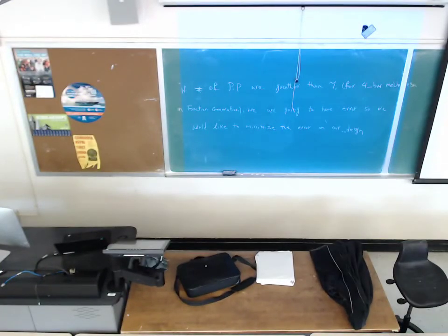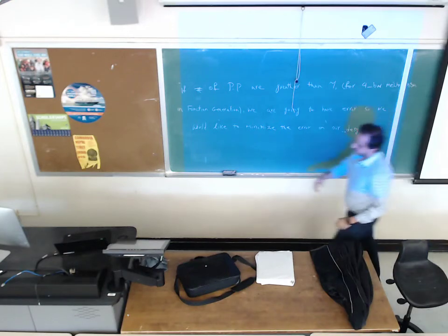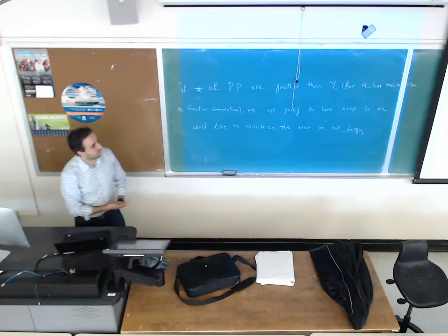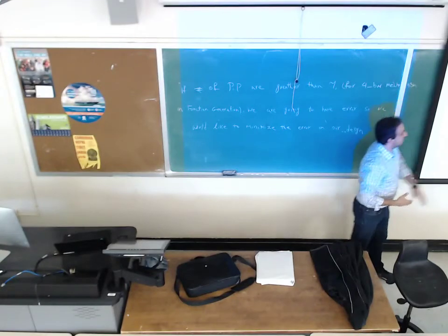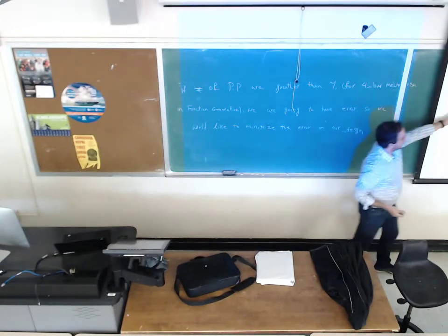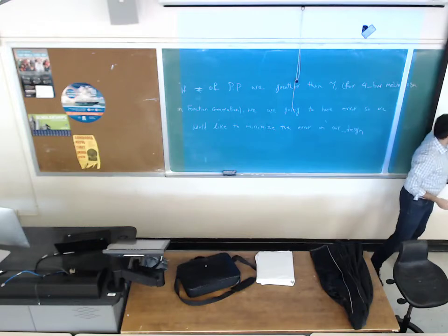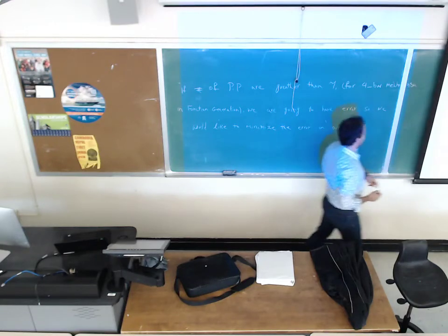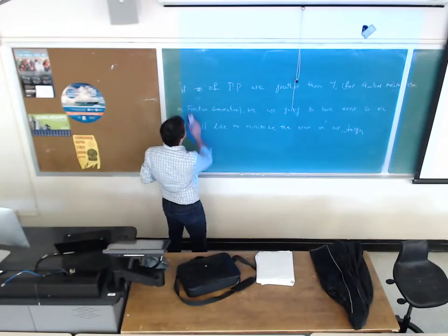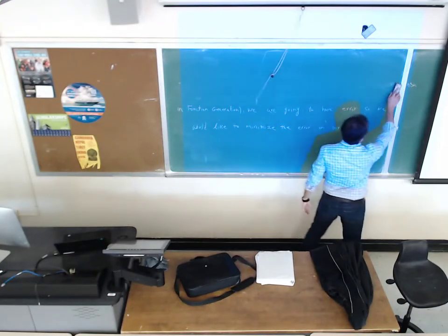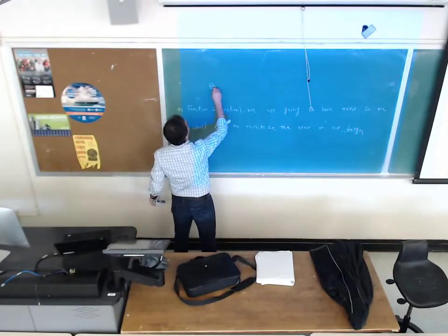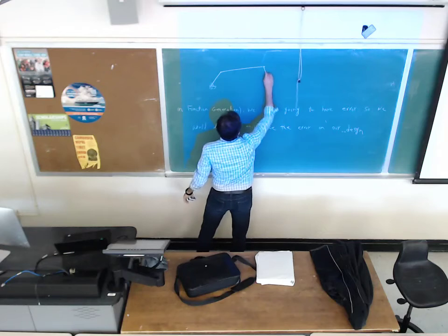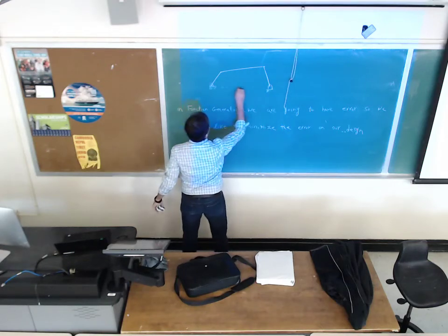If you have more than 7 precision points, for example, we would like to generate or synthesize a 4-bar mechanism such that it provides this desired correlation between input angle and output angle. When the mechanism is moving from the first precision point to the second precision point by 10 degrees, the output angle should move by 12.